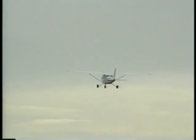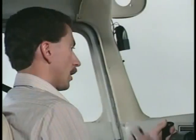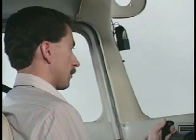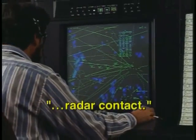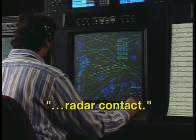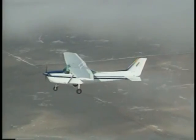After changing to the departure frequency, your initial call should include your ID, current altitude, and the altitude to which you're climbing. "Departure, Cessna 52241, 2,500, climbing to 5,000." By stating your current altitude, the controller can verify the accuracy of your Mode C transponder. "Cessna 241, roger, radar contact." Radar contact is used by the controller to let you know that your aircraft has been identified. However, it is your responsibility to maintain adequate obstacle clearance until the controller issues you a vector or other instructions.